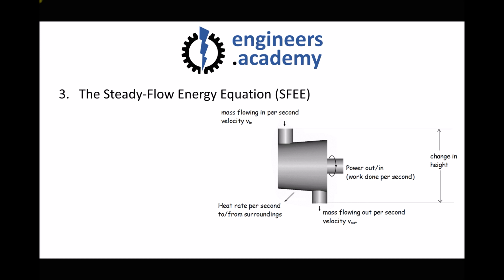So let's be a little bit more specific when we see how this applies to the steady flow energy equation. Now, because we have a mass flow rate entering the system and we have a mass flow rate exiting the system, what we're actually going to consider is the rate of change of different types of energy. So we're going to consider the rate at which kinetic energy enters the system, and we're going to consider the rate at which kinetic energy exits the system. We're also going to consider the rate at which potential energy enters the system, and we're going to consider the rate at which potential energy leaves the system.